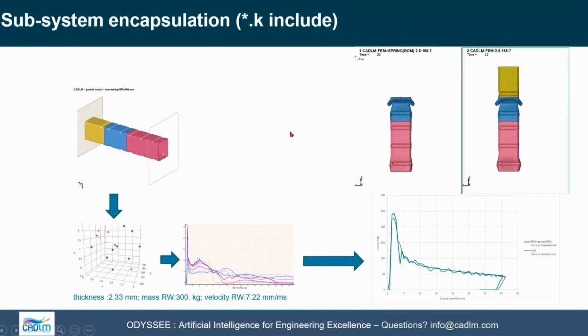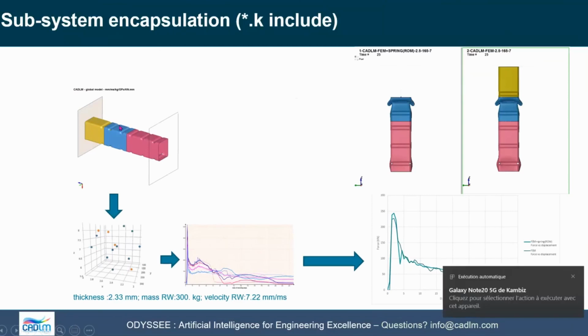So let's start with a simple example, which is also the simplest way of coupling LS-DYNA to Quasar that I wanted to show you. Let's assume I have here a box beam, and I want to do optimization, let's say on the pink and blue part, but the yellow part I don't really want to waste my time on, or vice versa. I want to study this part, not the other. So we intend to extract the yellow part and make it a parametric part, but we don't want to compute it anymore. That means we want to replace that yellow part by what we call a reduced model, which has 0 computing time. So the computation time will be spent here and not on the yellow part.